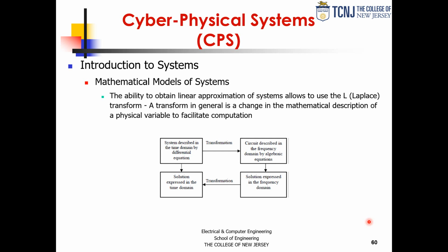For medical applications, the 60 hertz is really invasive to the measurement that you're trying to take. So coming up with efficient and good 60 hertz rejection filters is something that is in all the good type of medical equipment. So that's an example.